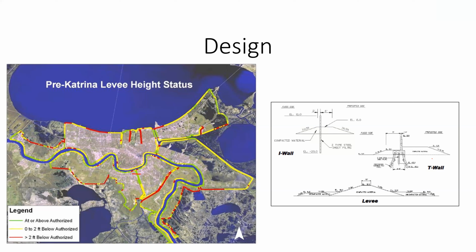So it allows the lateral displacement, because the lateral displacement comes from the point of fixity. If your point of fixity is not being developed, then you'll have more movement, right? That's the basic idea. But if you look at the T-wall, it is like a retaining system, and that retaining system is supported with the pile, or maybe not, but you always have more passive resistance because of its foundation. That's why the T-wall is performing better.